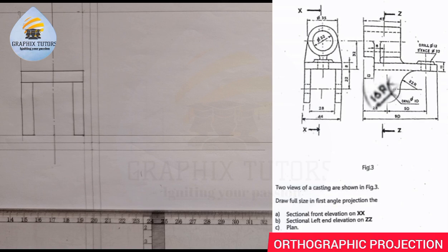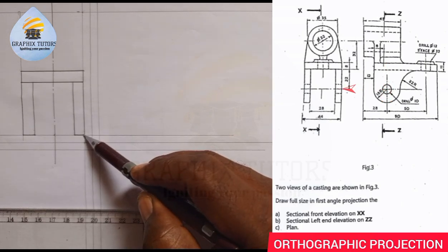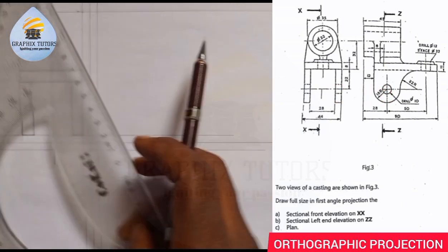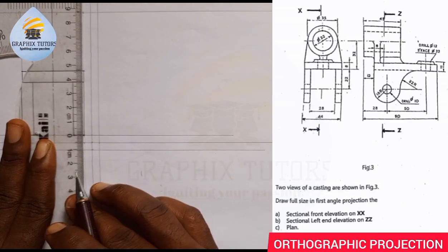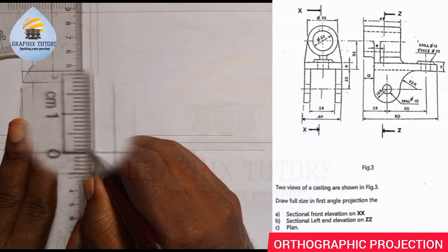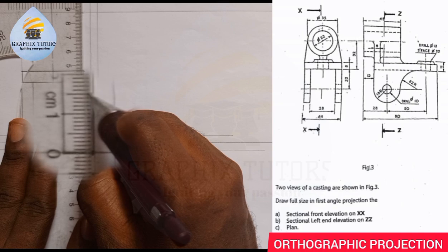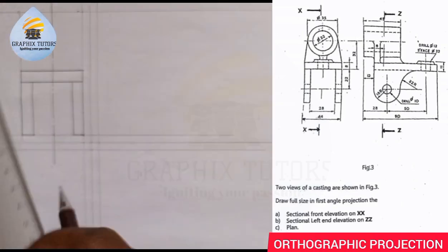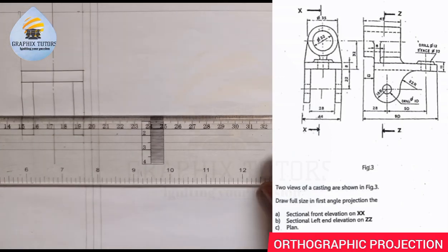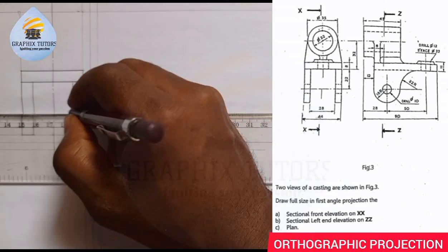Now, aside from that, the next thing that we should be doing here is that I'll measure 16, since the radius is 16, from this circle here to this end, this point here, 16. That will give me the center of this circle here. I'm going to measure 16 from here upward. So you measure the 16 from 0 to 5, this 5 here, that's 15, then 16. That will be the center, right?